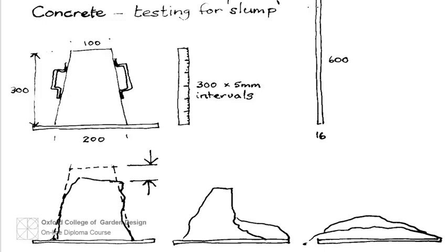Another method of producing thin, crack-free concrete linings for small pools and water canals is to use glass fibre reinforced concrete, known as GRC. Ordinary glass fibre would be corroded by the alkalinity of the cement.